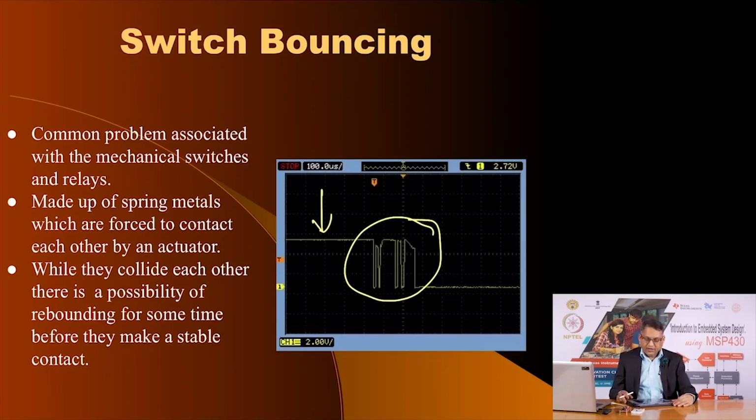However, it does not mean that every switch press will lead to so many ups and downs. In your case, there may be more. It is also possible that you will get even less bounce, or no bounce at all. So, do not get alarmed. This is an extreme situation, and we have taken several recordings on our oscilloscope just to identify a situation where it shows several bounces.